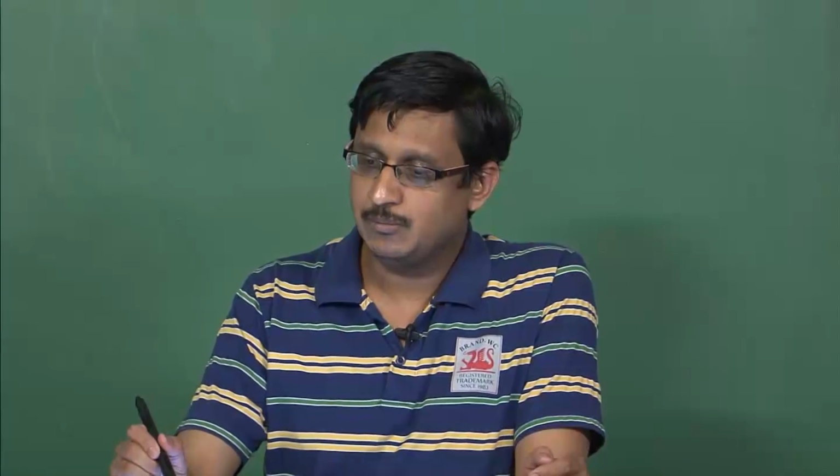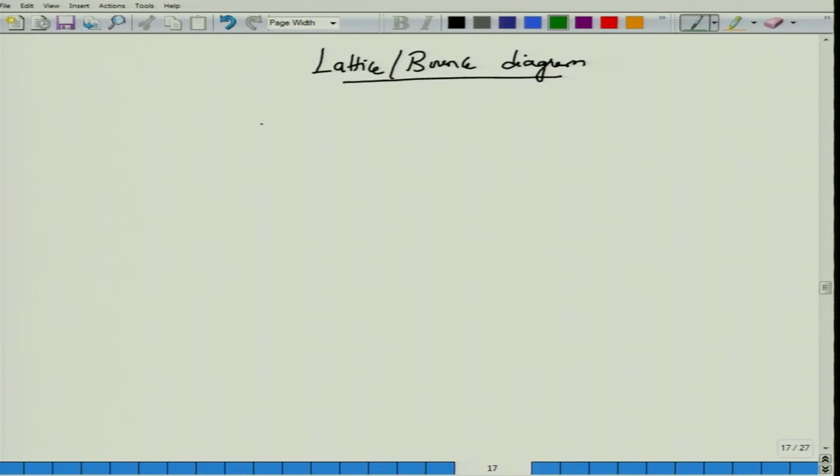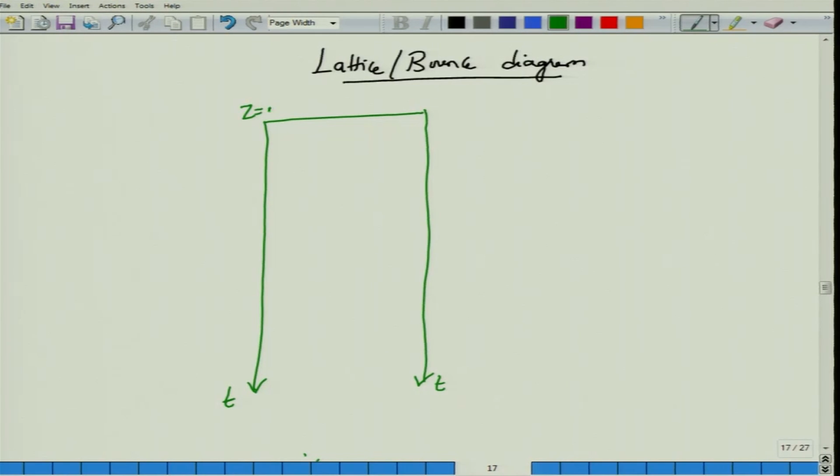So, the bounce diagram or the lattice diagram begins by first drawing two straight lines, and these lines are labeled along. These lines are actually the time axis, and the distance between the two will denote the source and the load points or the load reference planes on the transmission line circuit.